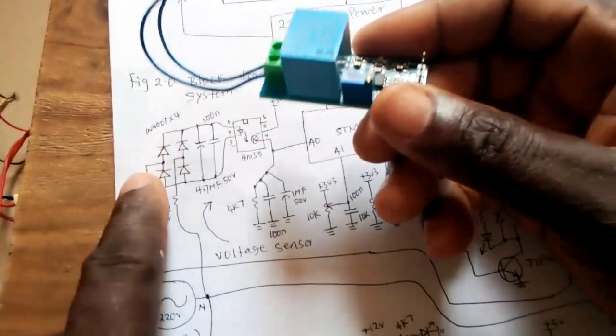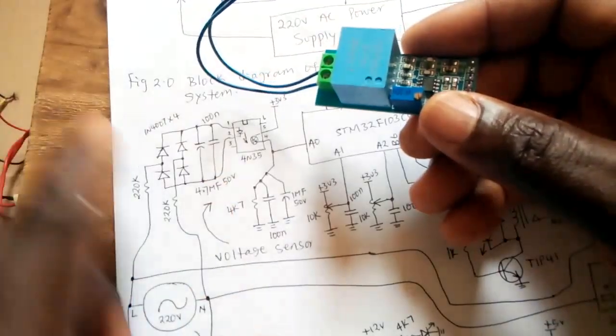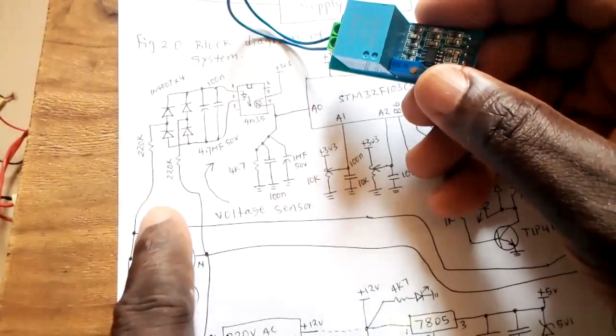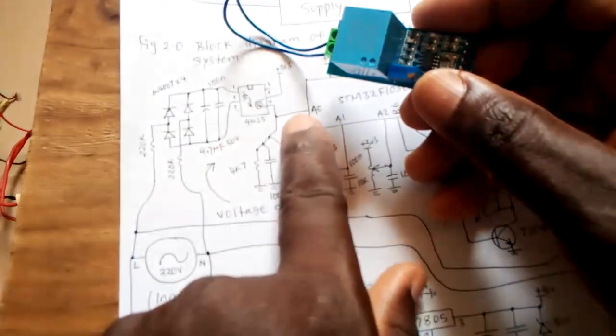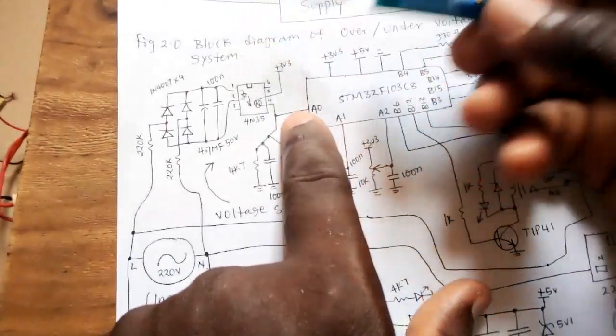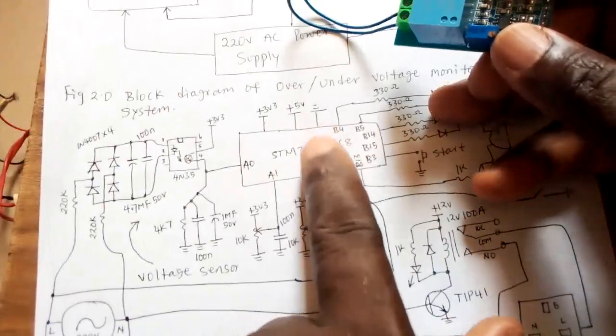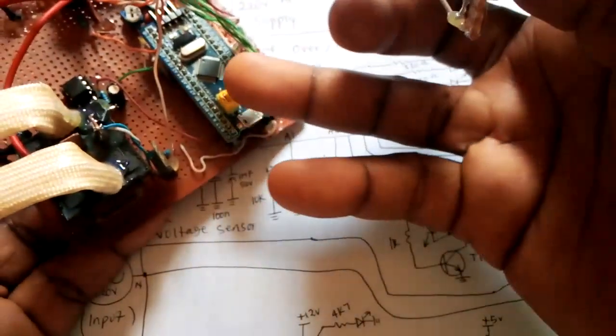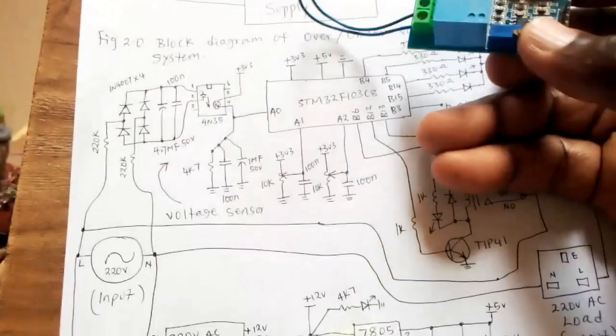I'm not really using it for that, only to know if the voltage is going high or low. Now, a proportional increase in this voltage will also give you a proportional increase in the DC voltage, which you can view when this is connected to your computer through USB and powered. Based on my program here, it will send the values to your serial monitor.